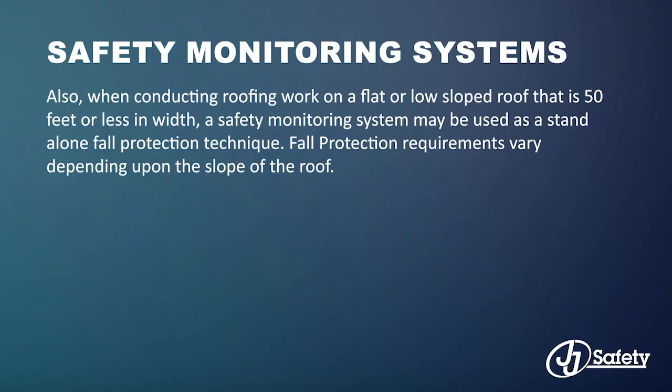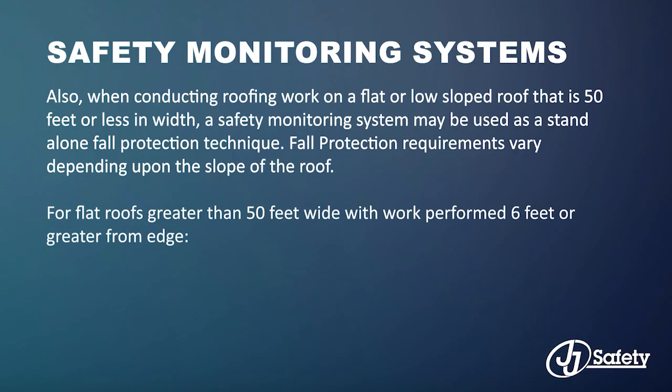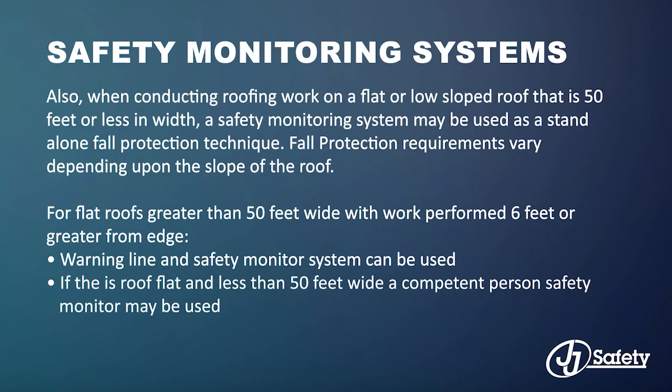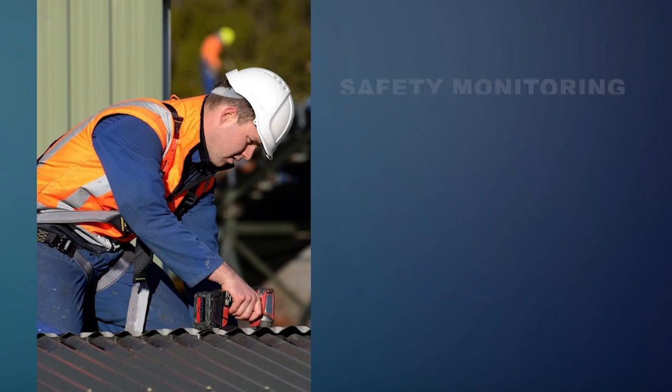Fall protection requirements vary depending on the slope of the roof. For flat roofs greater than 50 feet wide with work performed 6 feet or greater from the edge, a warning line and safety monitor system can be used, and if the roof is flat and less than 50 feet wide, a competent person's safety monitor may be used.